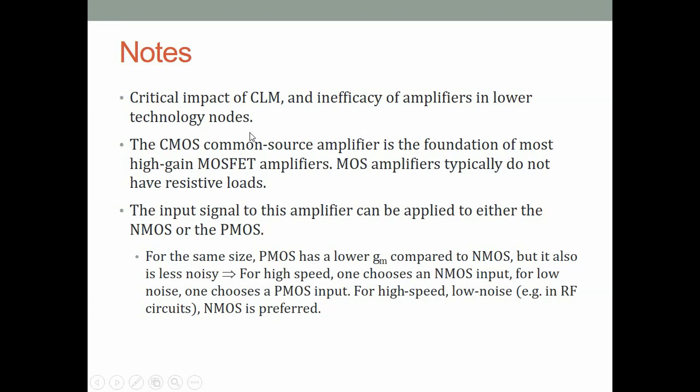20 nanometers is cool for digital circuits. It is totally uncool for analog circuits, specifically amplifiers, because you will not get any gain. You will probably get a gain less than 1 for a 20 nanometer MOSFET. Alright. Okay, so that is an important note here.